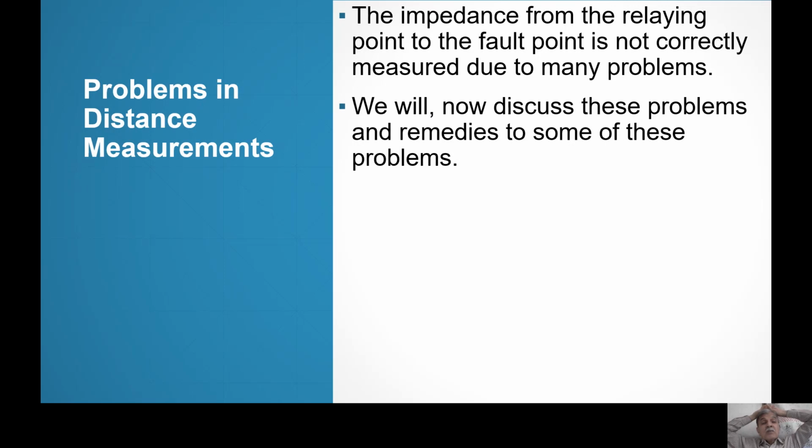But yet, there are many problems in distance measurement. We'll take them one by one. We mean that the impedance measured by the relay is from the relaying point to the fault point. But we forget about fault resistance.